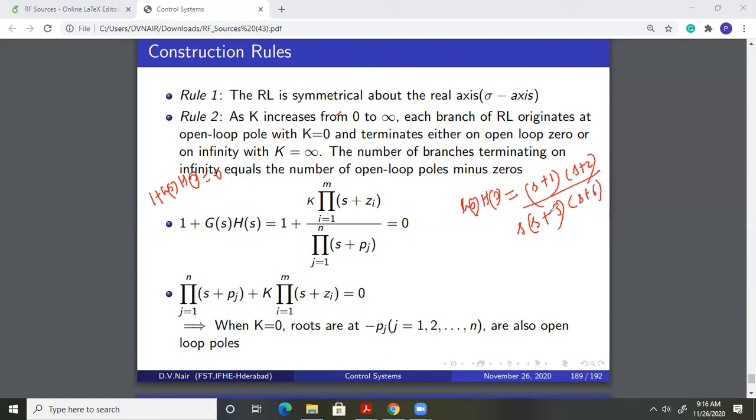So we know that this form of representation is a pole zero form, wherein in each factor the coefficient of s is unity, and the right hand side of the plus sign in each factor gives us the poles and zeros. So for this, what will be the poles and zeros? Poles will be one at origin, one at -3, and one at -6. And what will be the zeros? One zero will be at -1, by the O symbol we represent a zero, and the other will be at -2. That is what it means.